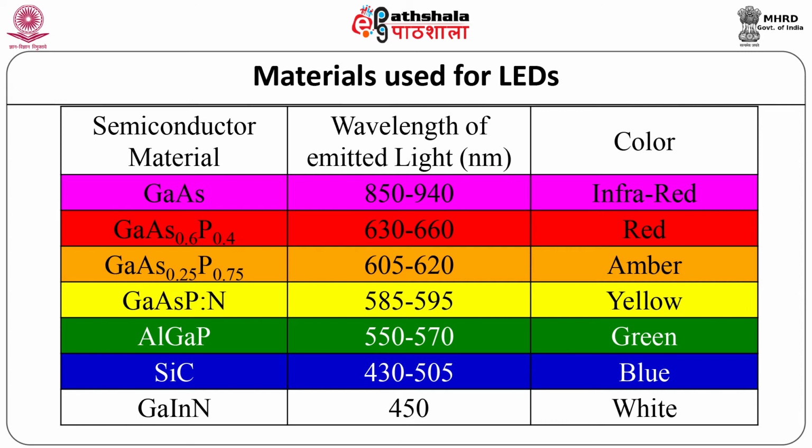Thus, one should remember that the color emitted by an LED is not determined by the coloring of the LED's plastic body, although these are slightly colored to both enhance the light output and to indicate its color when not illuminated. Most light emitting diodes produce just a single color of light. However, multicolor LEDs are also available that can produce a range of different colors from within a single device. Most of these are actually 2 or 3 LEDs fabricated within a single package.